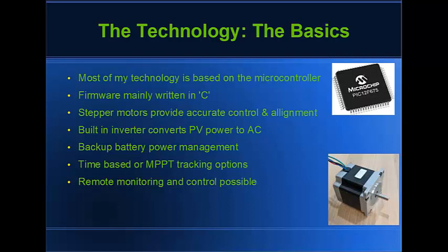Most of the firmware I write for the microcontrollers will be written in C. Stepper motors are motors which step only in discrete steps, and these are excellent for this application as they provide very accurate control of movement and alignment. A typical stepper motor steps in increments of 1.8 degrees, or that's 200 steps per one rotation.